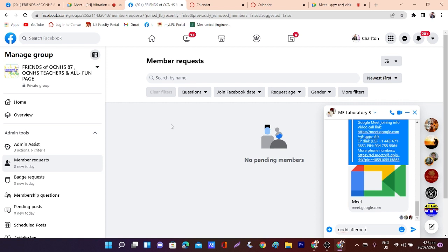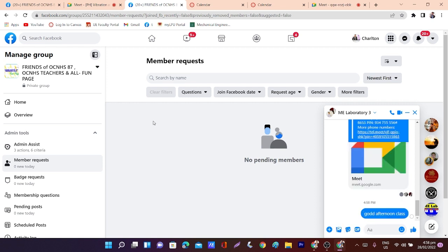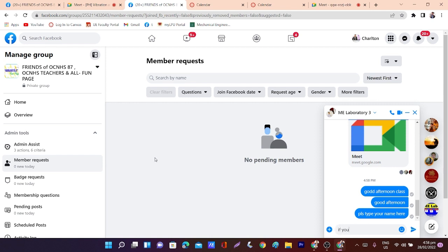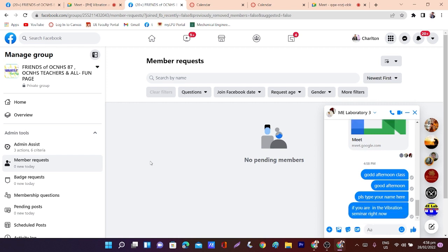You can check what happens to the stresses when you use a composite material instead of a traditional material. In addition to the pre-processing, we also have different post-processing techniques. Using these, you can look at the composite specific failures like buckling of the composites, or wrinkling, or delamination of the laminates. All these, which are very specific to composites, can be verified using the Composite PrePost. This tool is also part of ANSYS Mechanical.